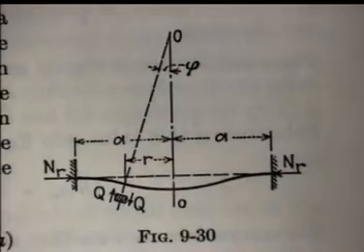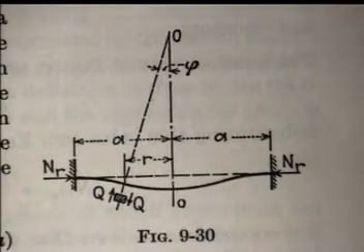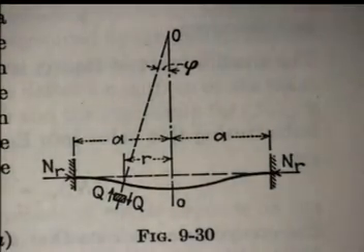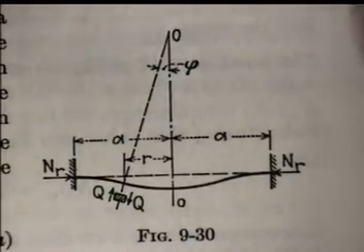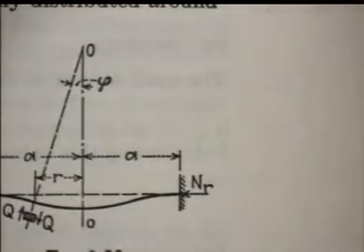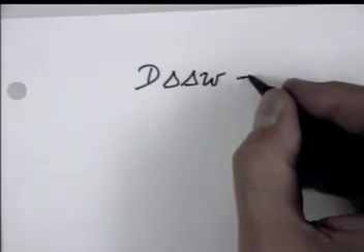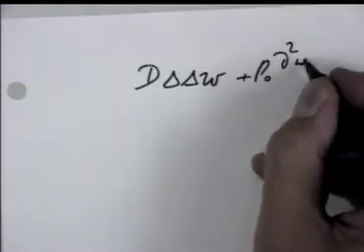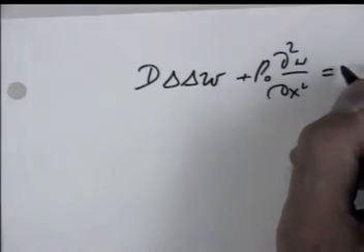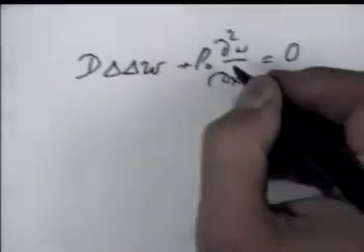Now, what happens is that in this particular case, we talk about axisymmetric buckling. So, look please. In plate buckling we had D del del w plus P0 d2w dx squared equals 0, yes?